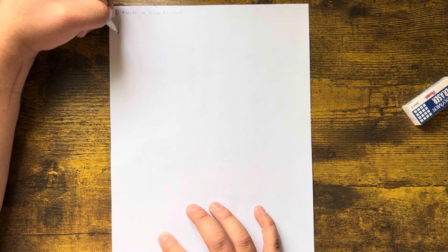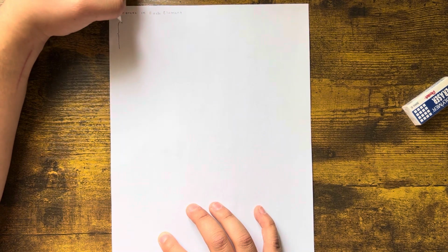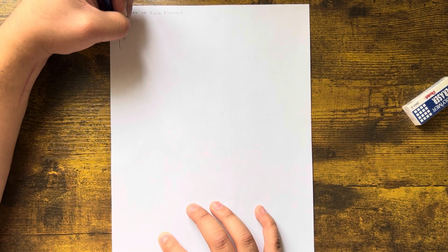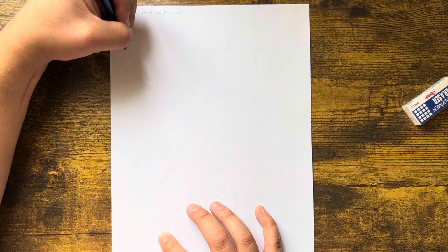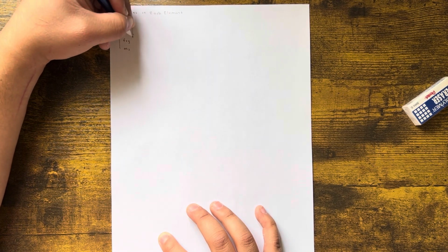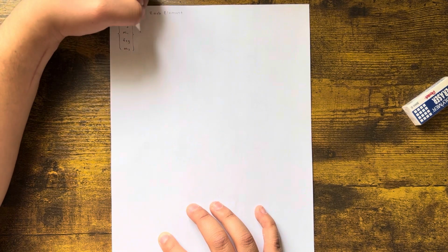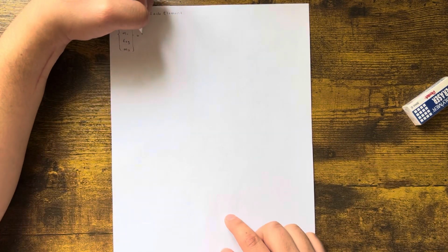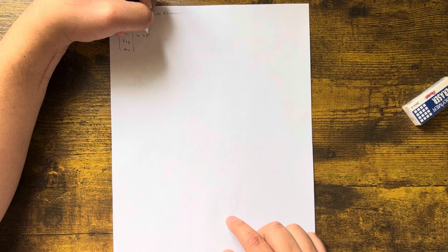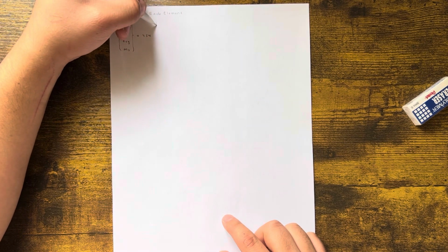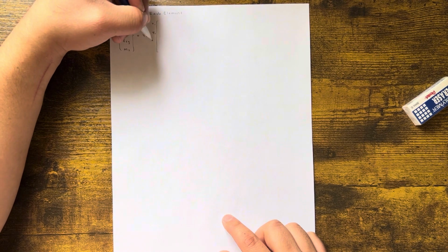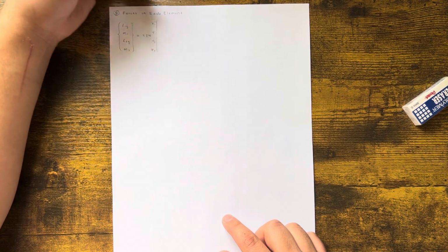In this case, it's one element, so we're going to have F1Y, M1, F2y, M2, okay? It's going to equal the stiffness of that element, which we already determined, EI over L cubed was 434, and that is between nodes V1, Phi1, V2, Phi2, okay?